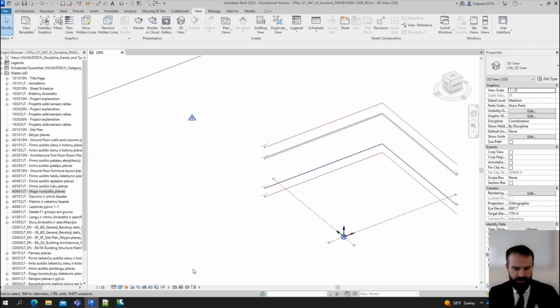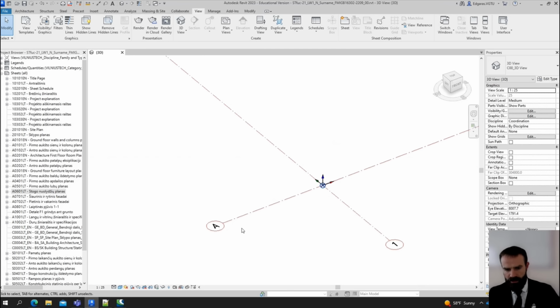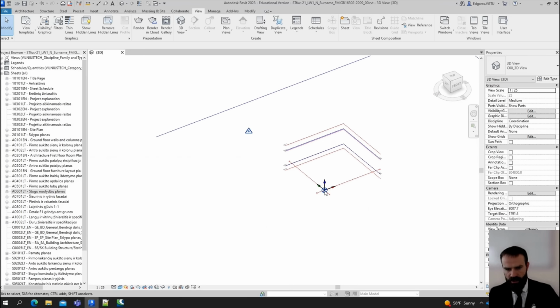So internal origin is in all the programs, AutoCAD, Inventor, SolidWorks, any program which has graphical elements has X, Y, Z coordinates and internal origin of any design. Based on Autodesk recommendations, base point and internal origin should always be in cross section of A1, and it should represent the base point of the project.